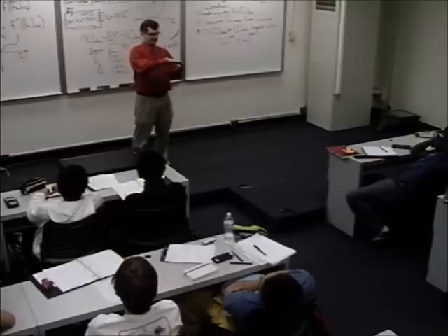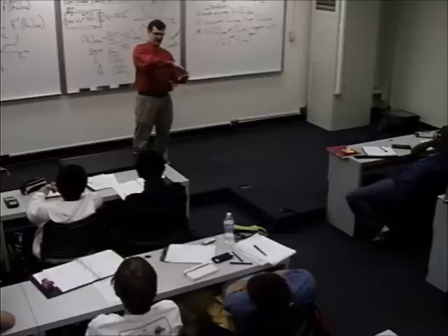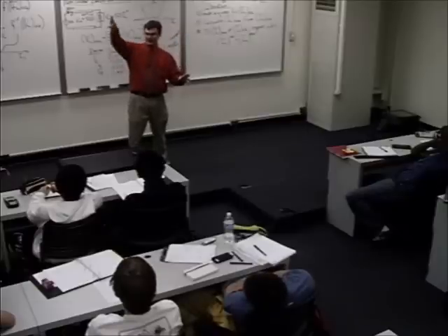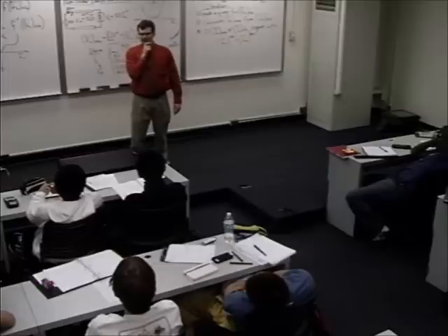We'll talk about the tunnel diode when we come back. That'll be an interesting scenario to look at. That actually has a VI curve where the I, as a function of V, jumps up, then jumps back down, and then jumps back up again. So there's a region in space where it's not even invertible. You've got to pick which solution you want. There aren't that many scenarios where that'll come up.